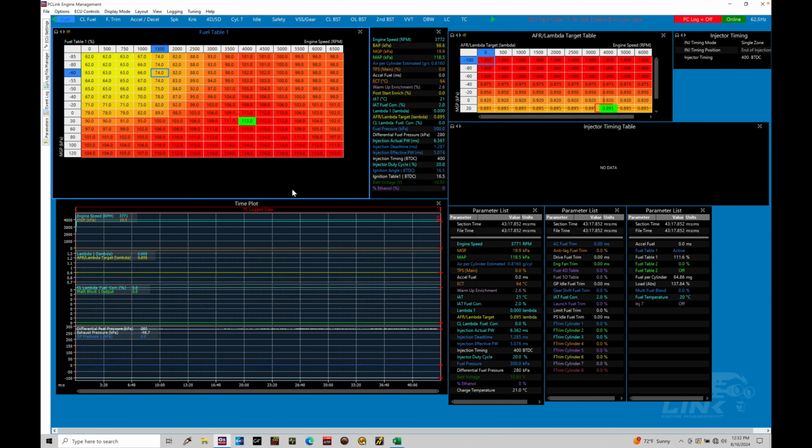And then as we're moving through most of first gear, that slip is really high. For traction control to really work properly, we need to have a relatively consistent slip in terms for the calculation to perform. So this kind of dynamic situation where we launch the car is very problematic with traction control, which is why we want to work with an advanced launch control like this.